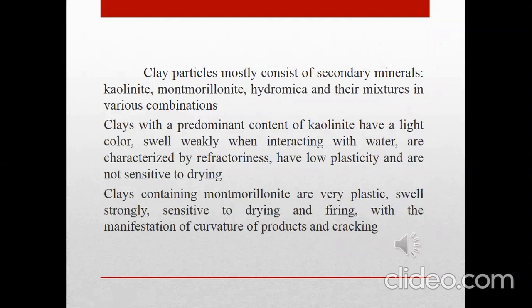Clay particles mostly consist of secondary minerals: kaolinite, montmorillonite, hydromica and their mixtures in various combinations. Clays with a predominant content of kaolinite have a light color, swell weakly when interacting with water, are characterized by refractoriness, have low plasticity and are not sensitive to drying. Clays containing montmorillonite are very plastic, swell strongly, and are sensitive to drying and firing, with the manifestation of curvature of products and cracking.